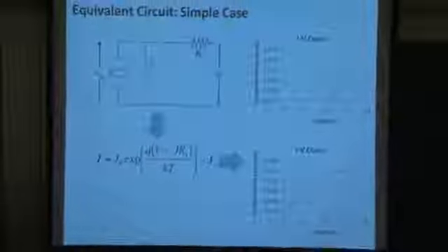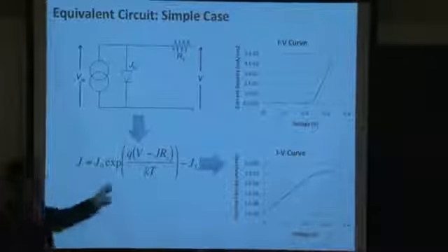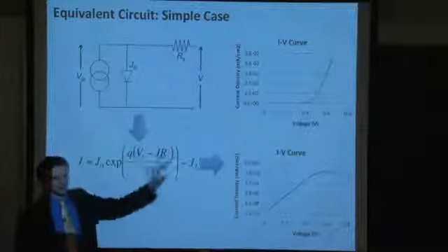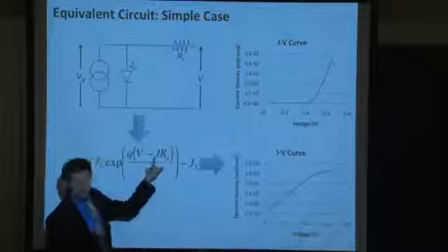Yes, Ashley? So in this curve, it looks like the series resistance really only starts to have an effect once you have a higher voltage. Absolutely. And you can begin to see that directly from the equation right here as well. Take the limit of low voltage and the limit of high voltage. Or another way to put it would be the high current, really.